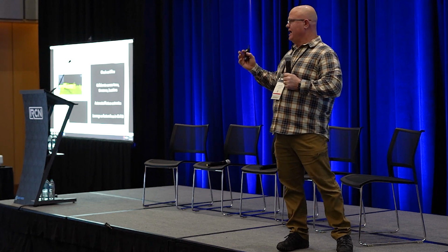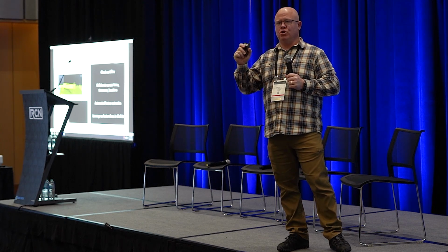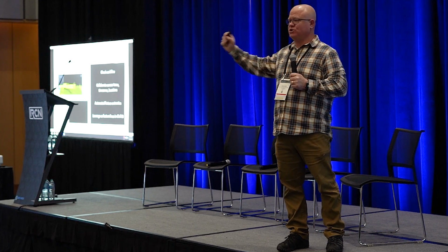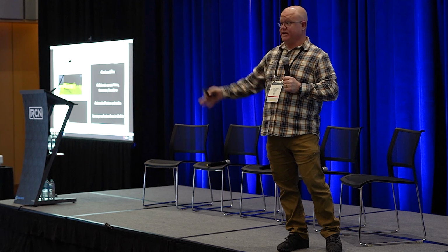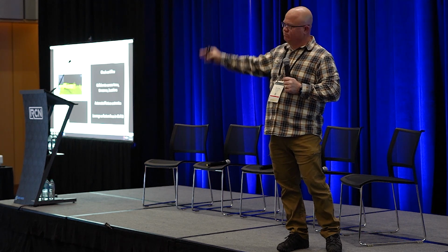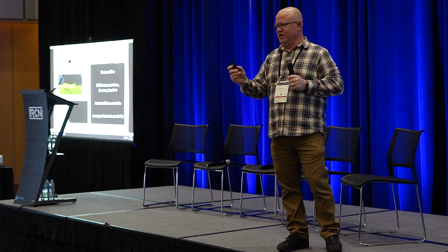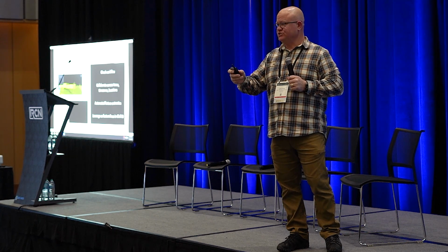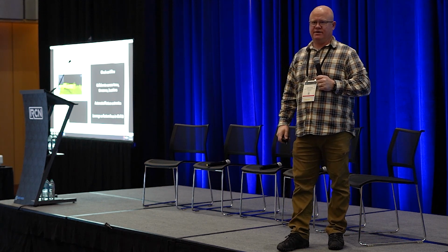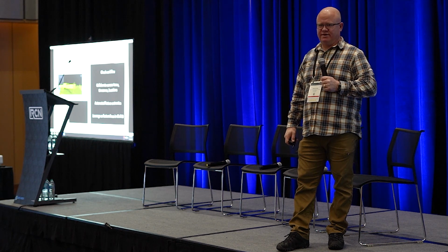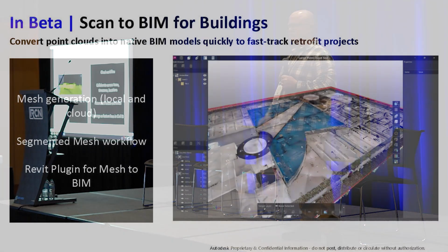So I don't know if any of you have ever built a corridor on a roadway, but you know that on the edge of that lane, if you've got it targeted to something and that target changes, that corridor will change. I used to call it the chicken wing. It'll move up and down, do whatever you want it to do, move in and out. So if that data changed that you were targeted to from ArcGIS Online, that corridor would automatically update, which means you don't have to do anything except watch it update and recontour. It's huge time savings.